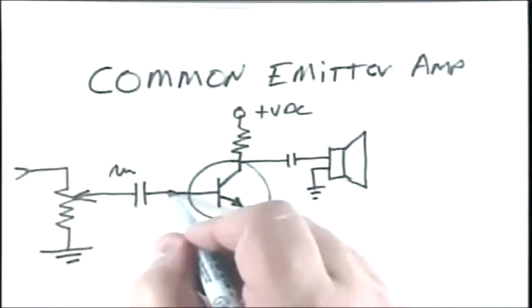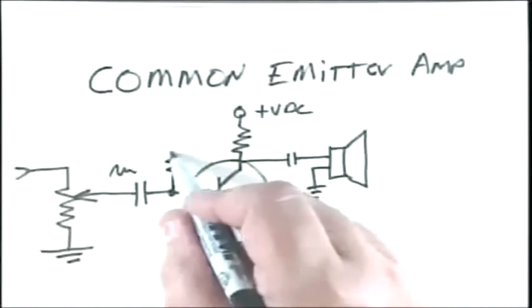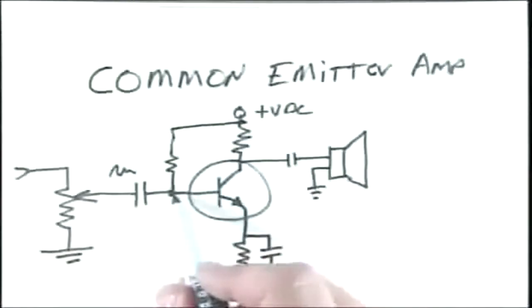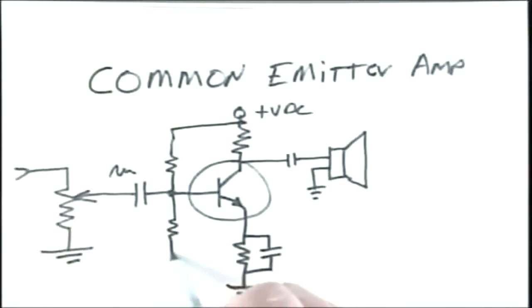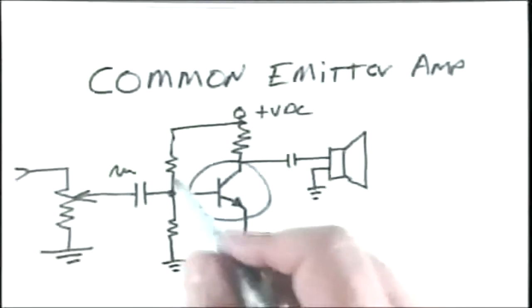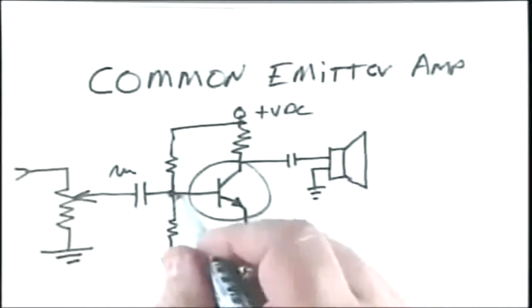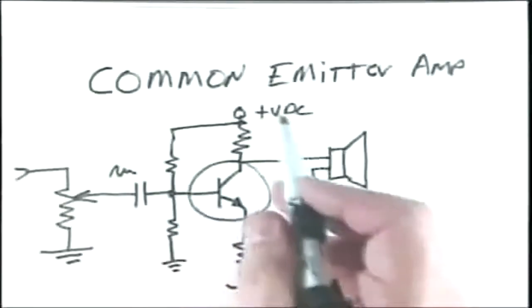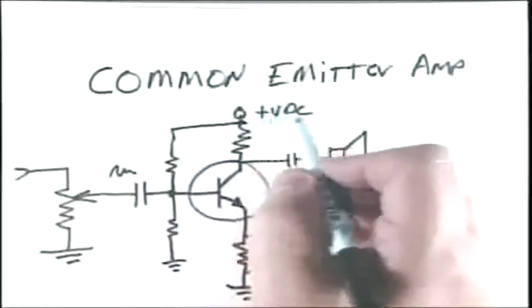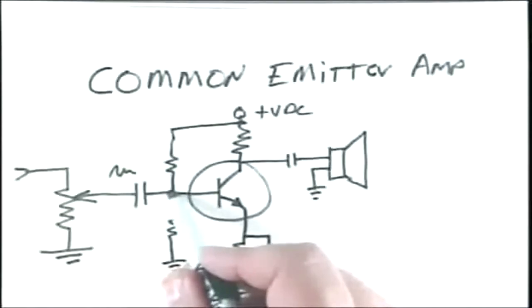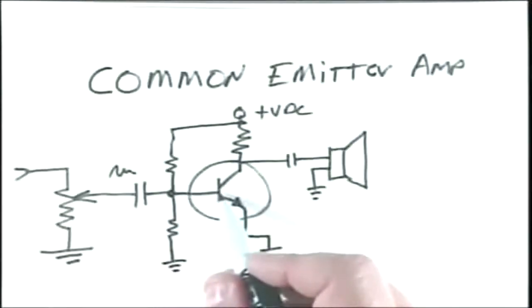We're going to put a resistor here and connect that to the positive voltage. We're going to put a resistor here and connect that to ground. Now, depending on the values of these two resistors here and here, I can make it any voltage at this point from whatever the positive supply voltage is to ground. And so I pick the right bias point to allow this transistor to be in the middle of its conduction point. And so once it's sort of operating but just barely,